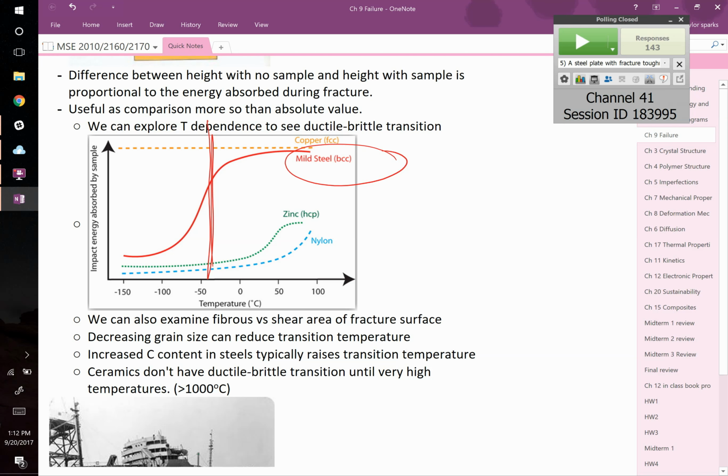But not all materials have this behavior. Some it's really remarkable. So some types of steels, this is a big deal. Takara, question? Great question. Your ductile transition could be associated with a phase change. I'm talking about a single phase, where increasing temperature doesn't make it more brittle. But you're right. If you go from a low temperature phase to a high temperature different phase, that could be more brittle. So that's actually a really good observation.